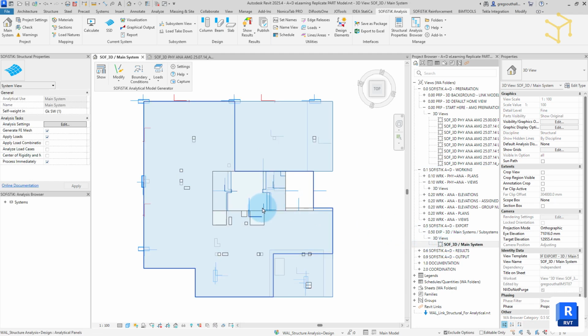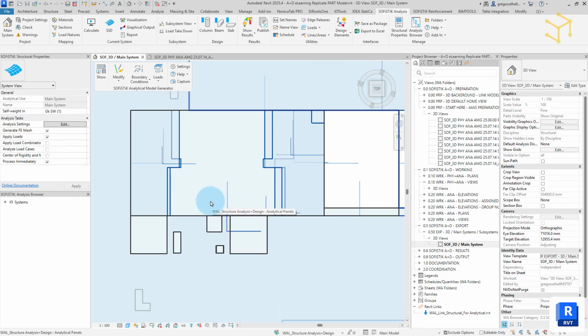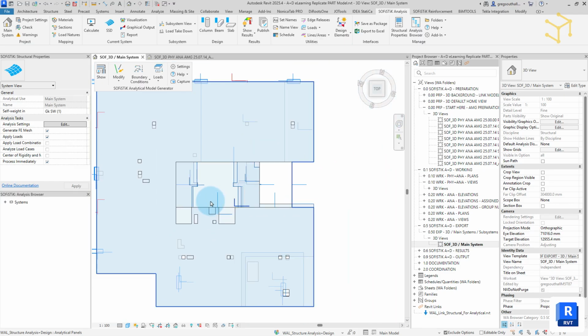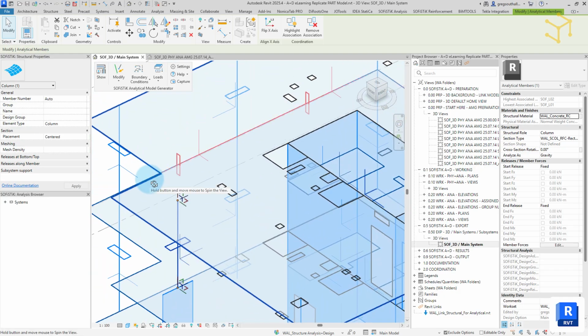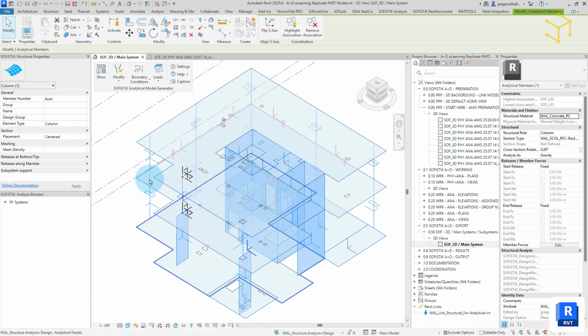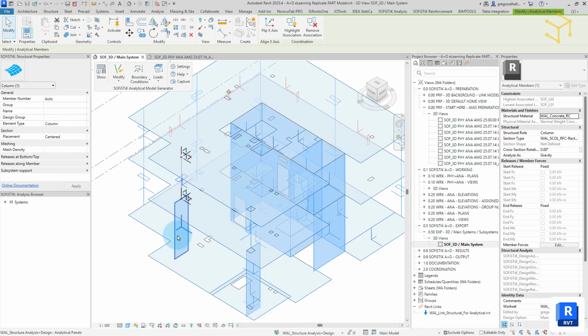Recall the only changes made were to the substitution of the blade columns. We can see AMG has generated the remaining structure as in the first iteration, but has now substituted the 1D columns with 2D planar walls of the same dimensions in length and thickness.